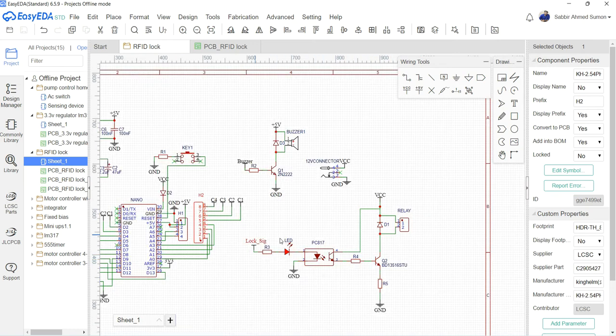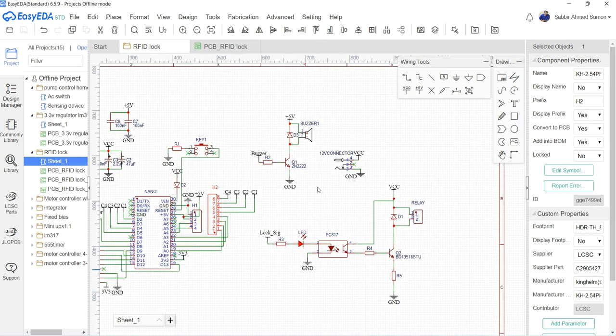So what this does is, there is no direct electrical connection between the Arduino and the relay. Actually, the relay or lock module may create noise, a fluctuation of voltage and current, which may destroy the Arduino or ATmega 328P microcontroller. So I haven't taken any risk. I have connected an optocoupler. It's better if the supply can also be separated, then full ground separation will be possible. And there are several types of ground separation. I will not talk about this in this video.